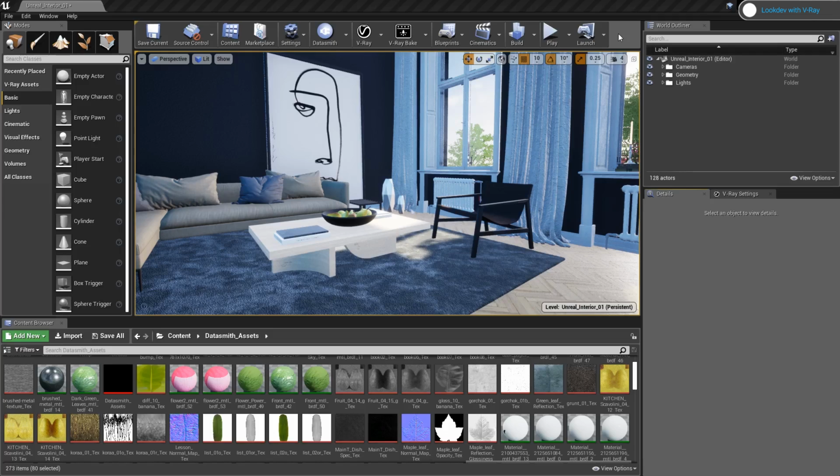Currently, the lighting looks wrong. There are no shadows and no indirect illumination present. What I want to do is tweak the sun in my scene and see the effects it has on the lighting. Typically, this requires a pre-calculation of lighting, known as light baking, which is a time-consuming process. As you can imagine, multiple iterations will increase the overhead quite a lot. For situations like this, I can leverage V-Ray's interactive rendering to get a better representation of how my entire scene will look, without having to do test bakes in my scene for every tweak.